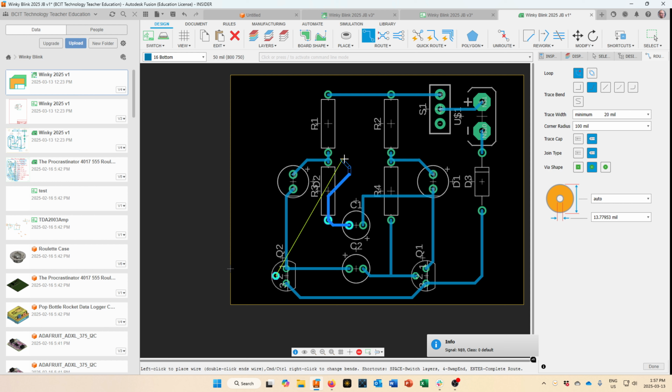And that's where having these nice big long flat resistors comes in handy because I can come around over here and finish my routing by scooting out and going underneath the resistor. And you might recall doing that when we designed the circuit boards by hand. So now I've got it all laid out about like this.